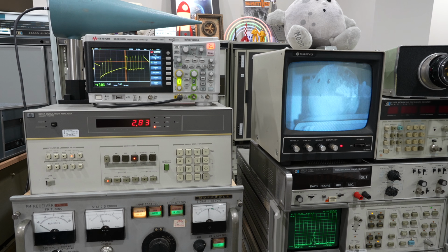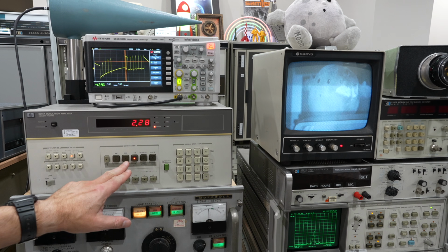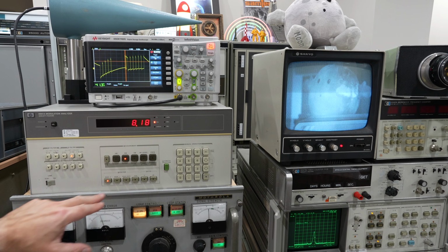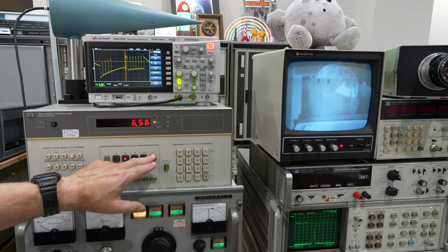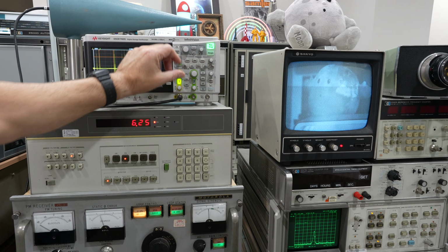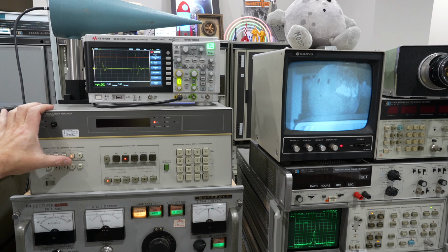Oh no, my brilliant HP receiver idea didn't work so well after all, at least not with that HP model. That's because although it can decode phase modulation and by extension PSK kinda sorta, this 1970s instrument is really meant for analog voice. The high bitrate is too fast for it and the low bitrate is too slow for it. Later instruments would do, but I don't have any, so there is no escape. I have to build a proper NASA PSK decoder.